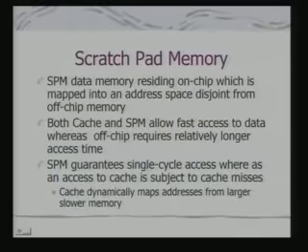So, the basic advantage of using SPM, on chip memory which is built with high speed RAM, is that it is a guaranteed access. If a location is mapped to SPM, there will always be a guaranteed access. So, typically your critical routines or most accessed routines are expected to be stored there, as well as data which is to be used very frequently or in a compute intensive fashion should be accommodated in SPM.